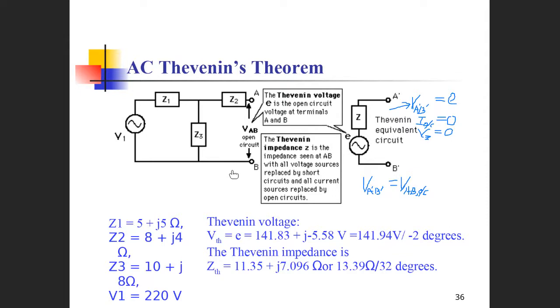So similarly, the impedance is equivalent to the impedance looking into the network from A and B with the voltage source short circuited. When the voltage source is short circuited, that means the total voltage here is zero. As a result, look, the current we can find out first, the current in this loop, when this is open, the current here